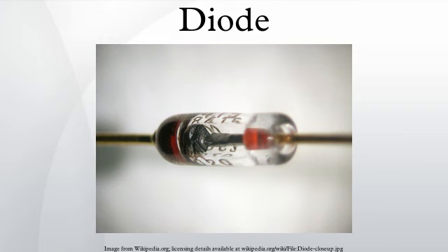voltage reference. The term Zener diode is colloquially applied to several types of breakdown diodes, but strictly speaking Zener diodes have a breakdown voltage of below 5 volts, whilst those above that value are usually Avalanche diodes. In practical voltage reference circuits, Zener and switching diodes are connected in series and opposite directions to balance the temperature coefficient to near zero. Some devices labeled as high-voltage Zener diodes are actually Avalanche diodes. Two Zeners in series and in reverse order, in the same package, constitute a transient absorber.